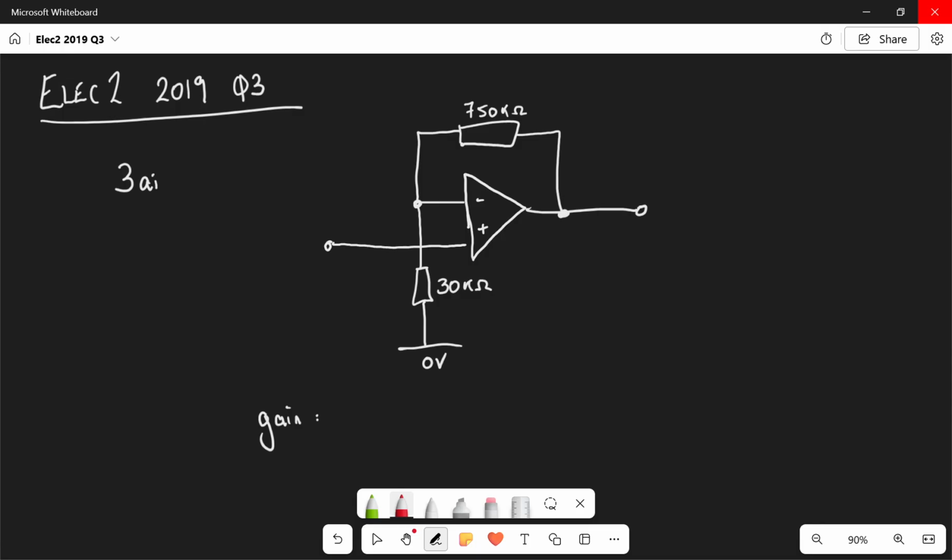And so for part 1, the question asks, the op-amps have a gain bandwidth product of 3 MHz. What is the overall voltage gain and bandwidth of the preamplifier?